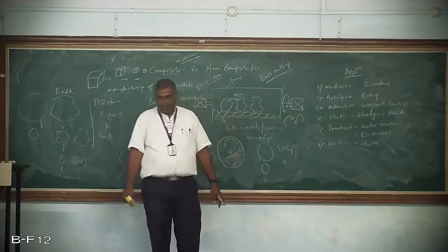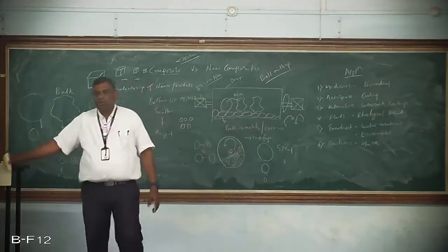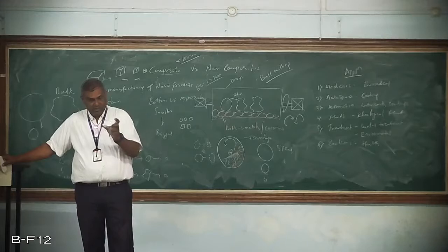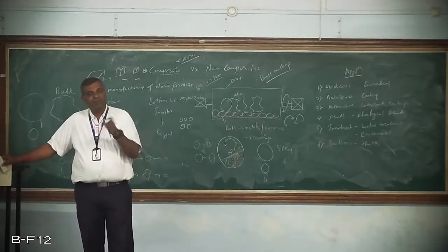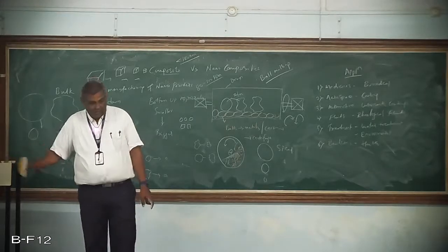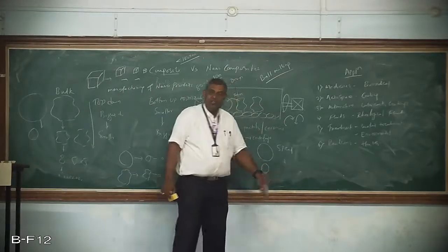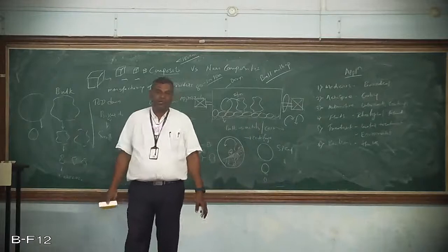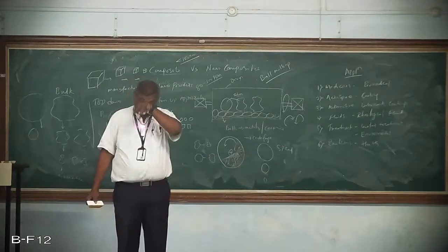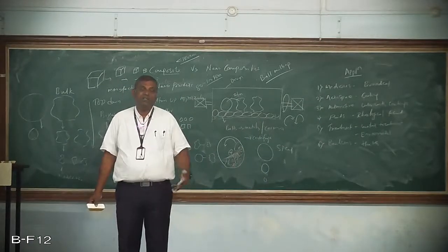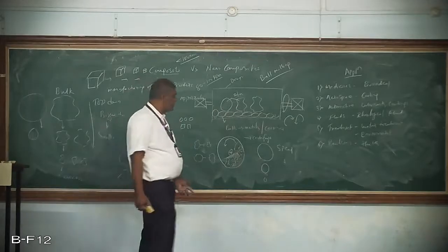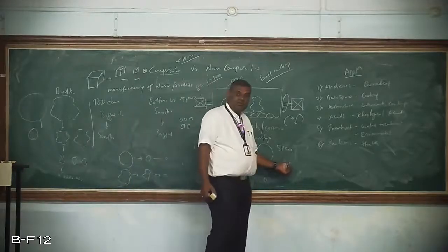So while doing this experimentation, or the optimization of the particle size and particle shape of the nanoparticles, we need to optimize the balls also. Hence this becomes very significant. So that is the advantage of using these different size balls. And the next is speed. What speed should this be rotated at?